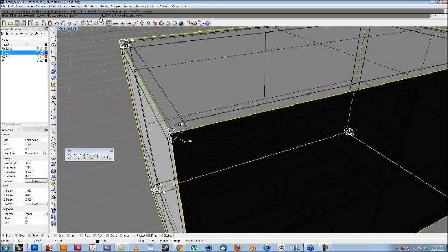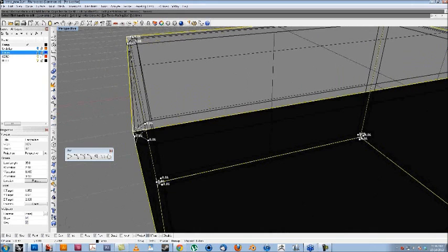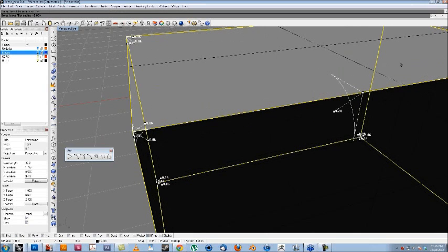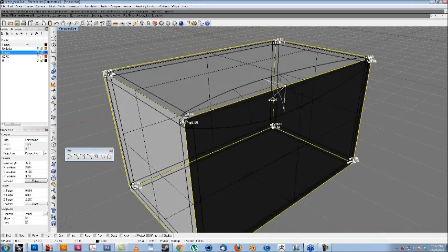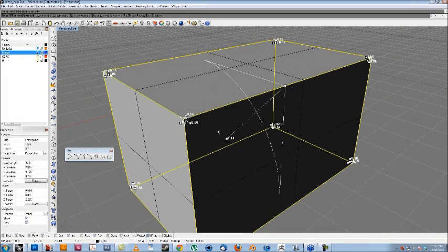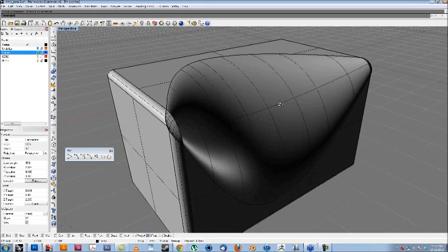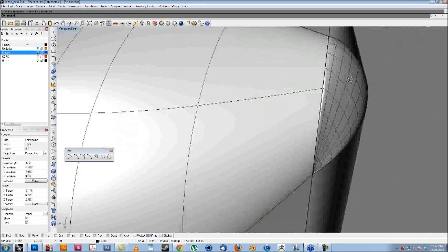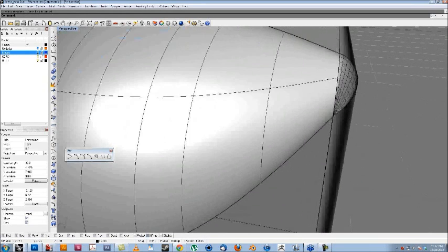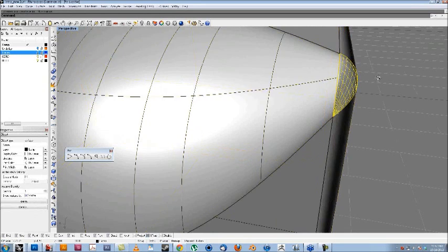Now there are all sorts of different sections in here that you can mess with. One I often use is I'll add a handle and then edit that handle and make it bigger or smaller to see how that affects my fillet. If I click on preview again now, I'm going to see that fillet there is not in conflict with anything, so I might get it to that point and see if that messes it up. And sure enough, it was able to make that big fillet, but not before messing up these corners.